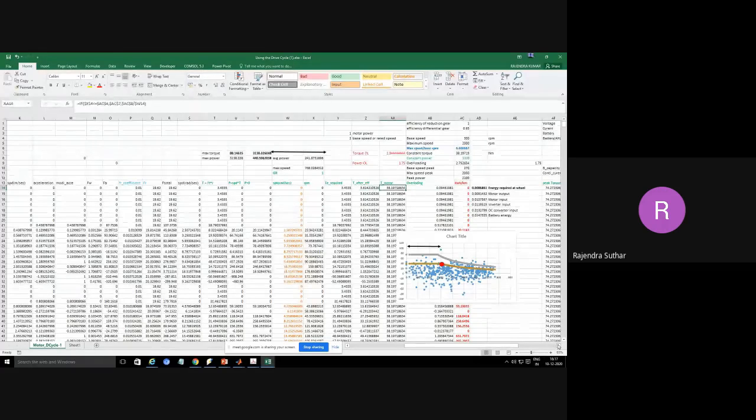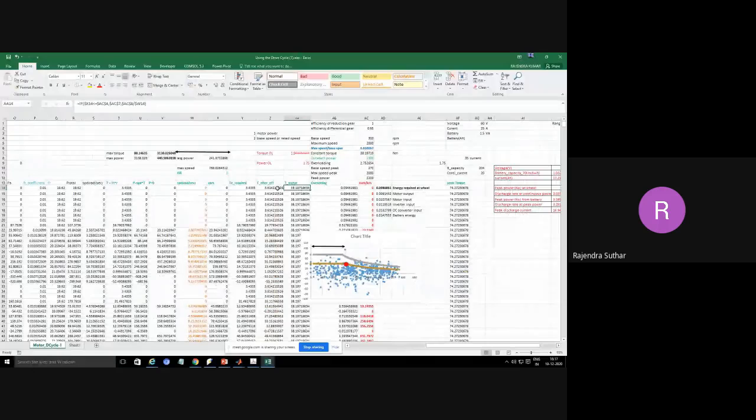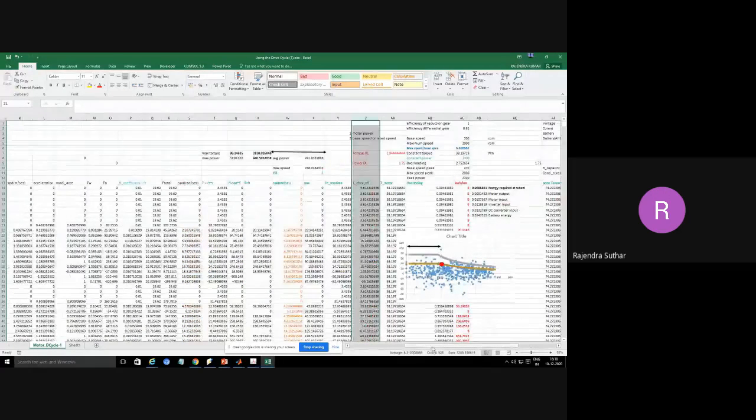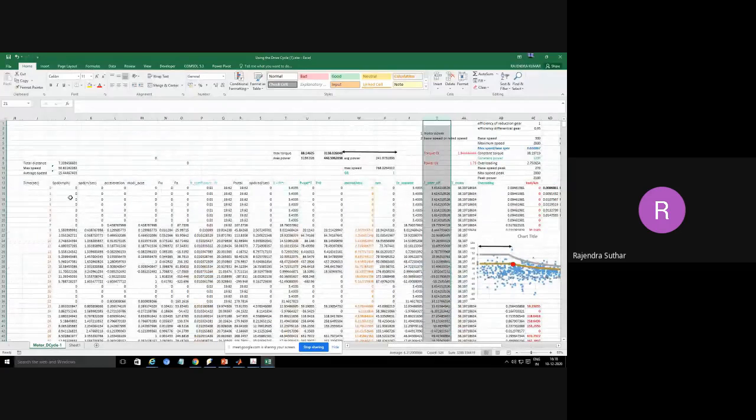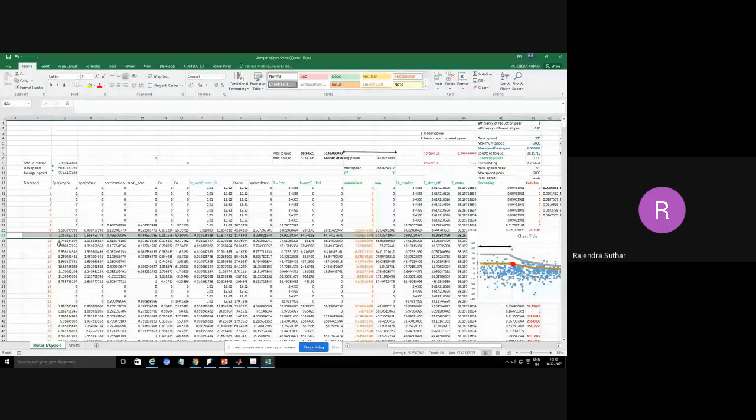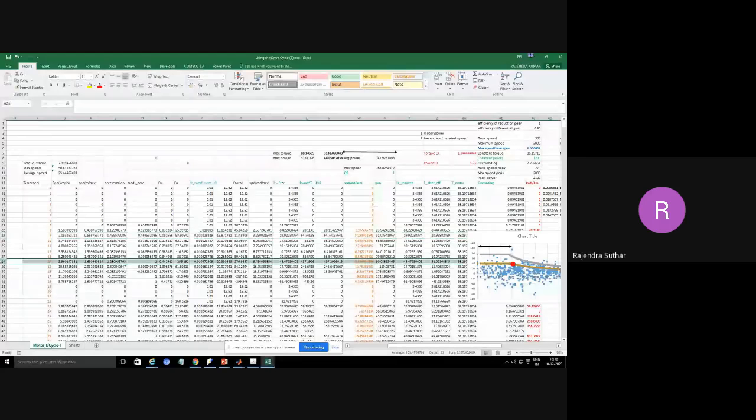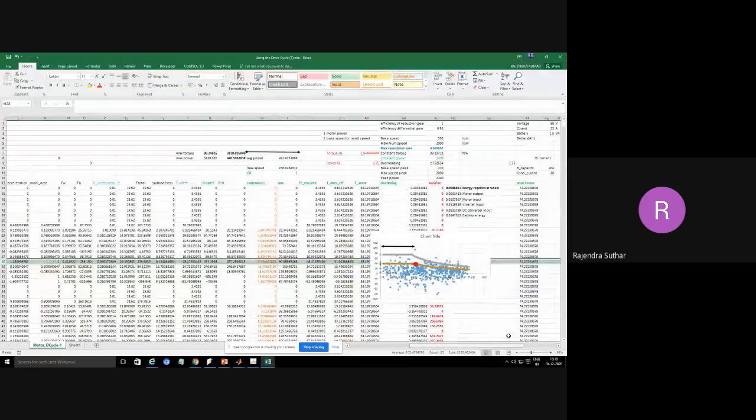And so finally, the data here in this Z column, this is the motor torque. So we have the velocity. Suppose we have some velocity here in this column 14. At that time our velocity is around 9, which is 6 kilometer per hour, and corresponding to that 6 kilometer per hour, we have the motor torque equal to 38 Newton meter.